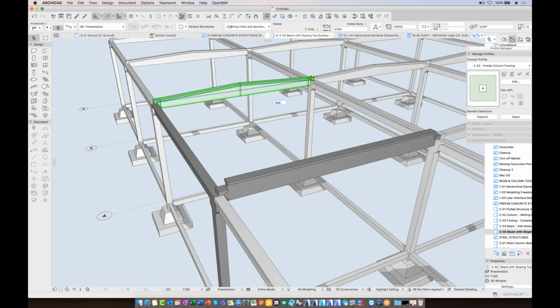But if I click here and just click on the reference line itself and then click add new node, that actually creates two new beams. So there's a new option here called split segment. And that will allow me to insert a segment into the beam. And I can just use the cursor to reference the midpoint of our neighboring beam.